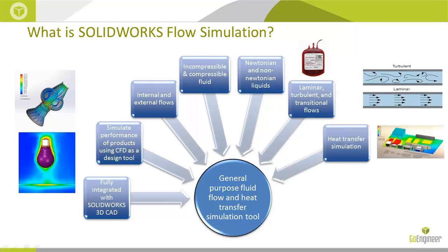SOLIDWORKS Flow Simulation also has a great heat transfer tool. So we're doing physical dynamics for flows, but also heat transfer. The reason it's such an excellent tool is that we're modeling the air or the fluid around it, so our convection is much more accurate than in an FEA tool where you're only modeling the solid.